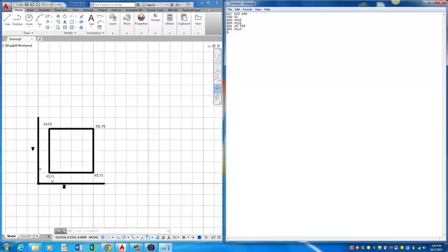Next move, G01, we're going to go to this point here. So it's X5, Y5. Next move would be, you guessed it, X5, Y1. And our last move is going to be G01, X1, Y1. So this is the code that actually drew this entire box.